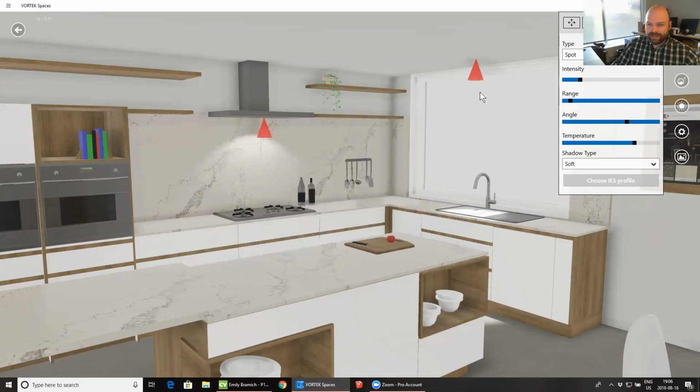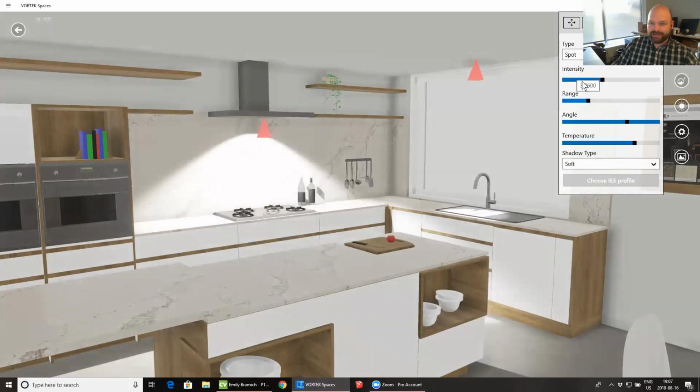You see in the beginning, since those two lights don't have the same range or angle, this is why you see the light that is blue on both sides. It just looks weird like that. It's not a bug or anything. It's really meant like that because they don't have the same settings. So you see exactly what was changed. For example, I could just change the intensity on both lights, but still leave the range different on the two lights. In this case, I want exactly the same range, same intensity.